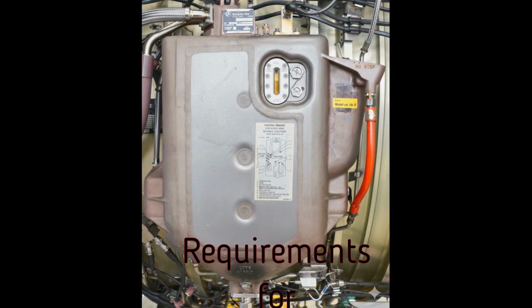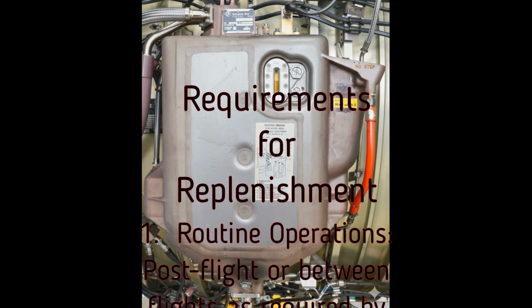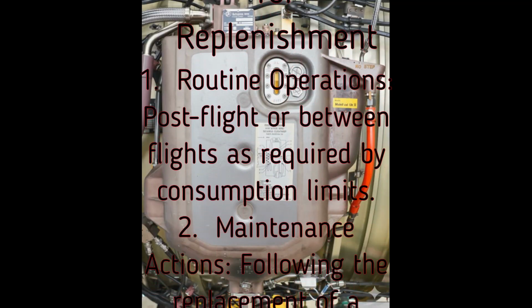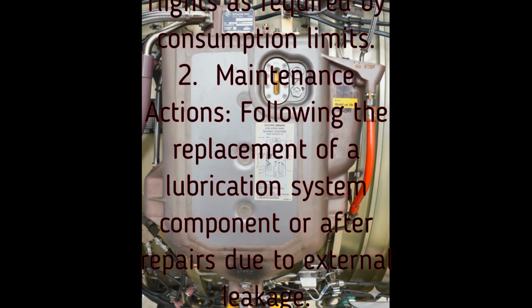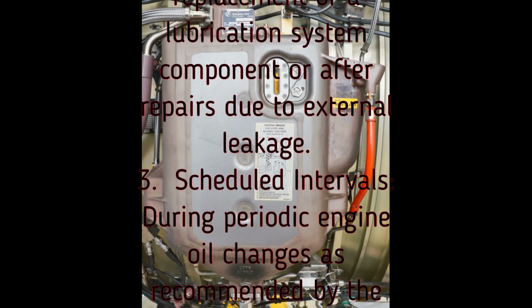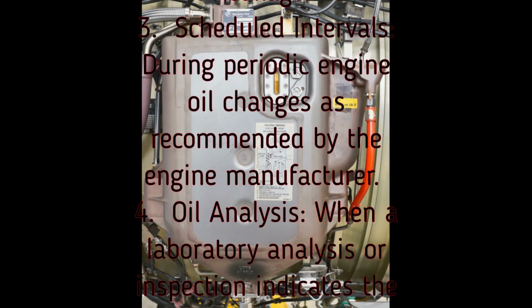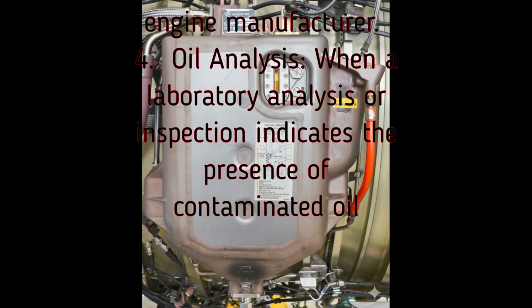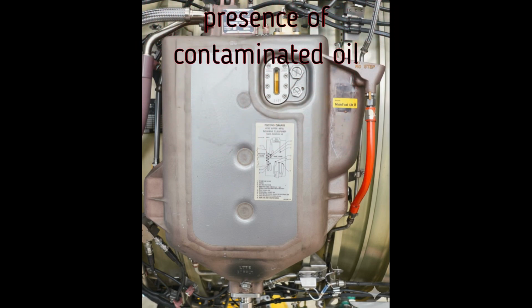Requirements for replenishment. The oil tank may require servicing or a complete oil change under the following conditions. 1. Routine operations, post-flight or between flights as required by consumption limits. 2. Maintenance actions, following the replacement of a lubrication system component or after repairs due to external leakage. 3. Scheduled intervals, during periodic engine oil changes as recommended by the engine manufacturer. 4. Oil analysis, when a laboratory analysis or inspection indicates the presence of contaminated oil.